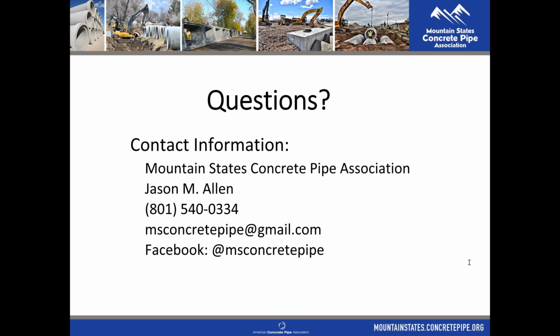We never know what condition those gaskets are going to be in, what happened during the original installation, or what happened during excavation of the old pipe. But if you're going to reuse a pipe, always use new gaskets. Contact one of the manufacturers, and they can talk to you about how they can get you some new gaskets. It's always better to use new, because we just don't know what condition the other ones are in. Even a visual inspection, I don't know if you're going to be able to see that. It's a really good one there.